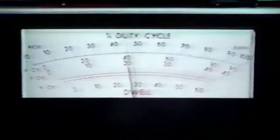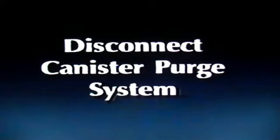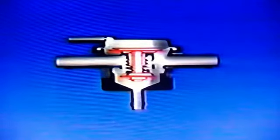In order to make the next diagnostic check, we'll need to run the engine until it goes into closed-loop operation. We'll be using the dwell meter or duty cycle meter to check for major fuel control problems in the carburetor. To do this, you have to first disconnect the canister purge system. There are two main types of purge systems, and each uses a different type of canister control valve.